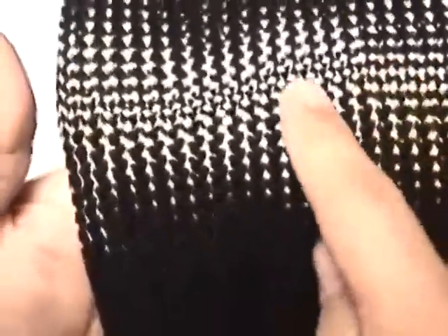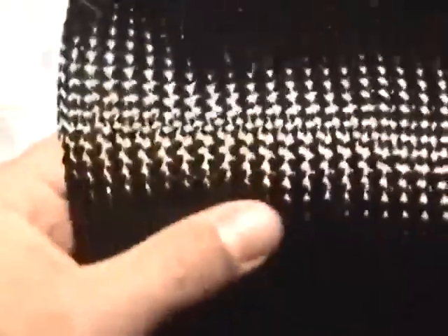When you stretch this out over the top of your model, you don't want it extremely stretched out as big as it can go. You'd like it to be kind of halfway in the middle, in a relaxed state, with the weave of the fabric going at about 90 degrees. That's about when it's at its strongest, about like that.